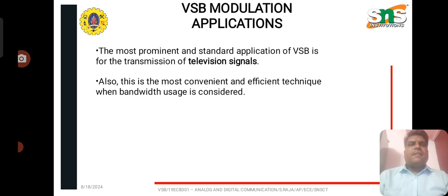If you watched my previous YouTube video, you clearly understood amplitude modulation, or double sideband full carrier. When we derived the efficiency of double sideband full carrier, the total efficiency was 33.33 percent. Since most of the power is wasted in the carrier and sidebands, the carrier is suppressed, and this is called double sideband suppressed carrier.